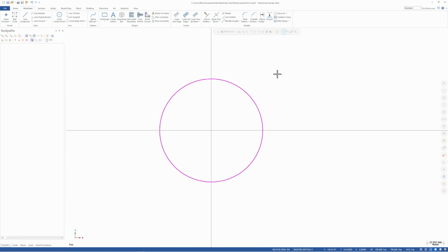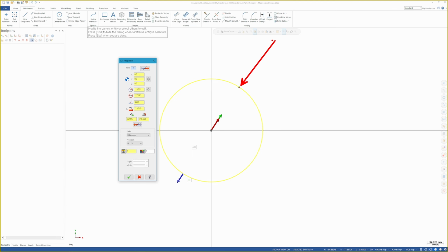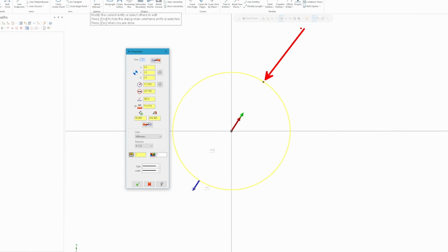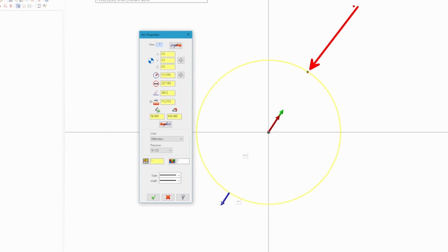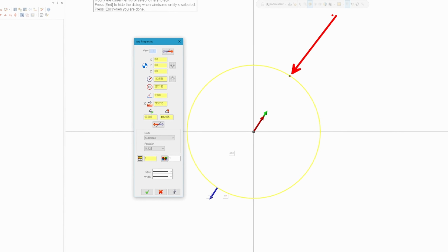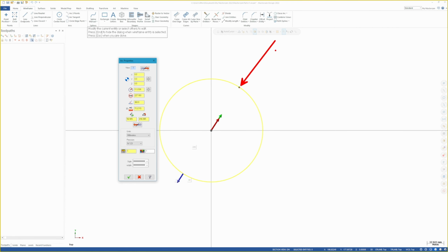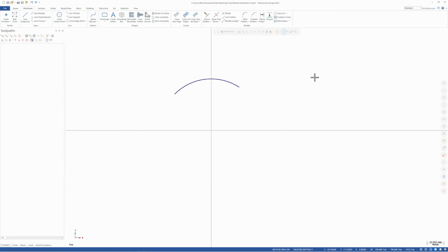a full circle. However, if I then go to analyze this circle, you can see that the start point and the end point is going to be at one or the other end of the circle that you closed. It doesn't reset back to a normal position. Like in Mastercam, typically 0 degrees is a 3 o'clock position here. That's normally what you see as a start point. And the clue to this tip is basically the command that I've just used, analyze. If I analyze this incomplete circle,